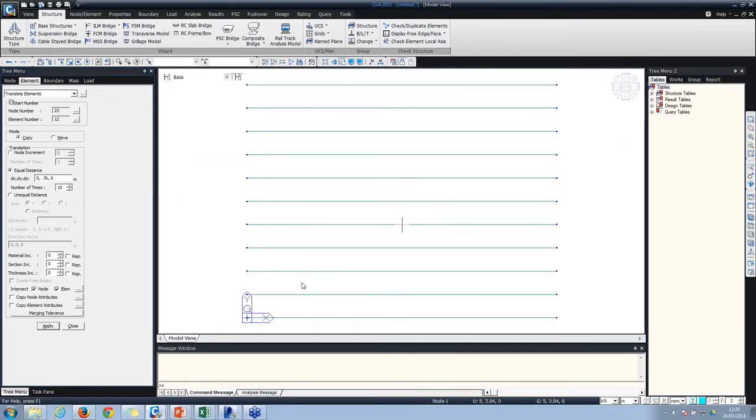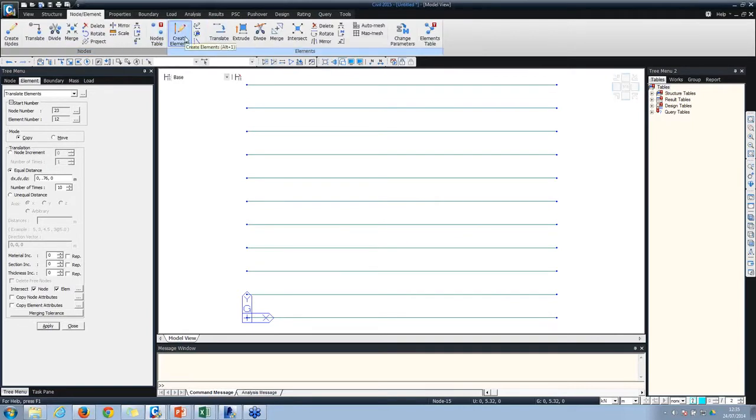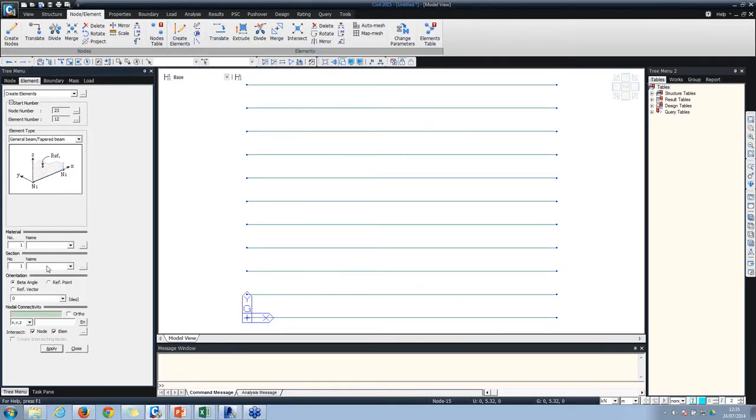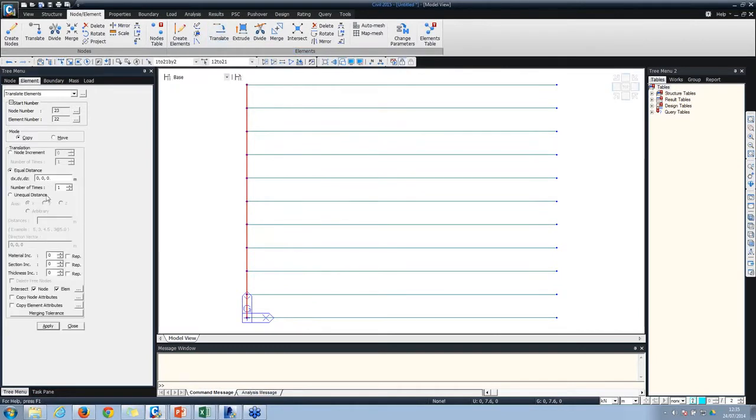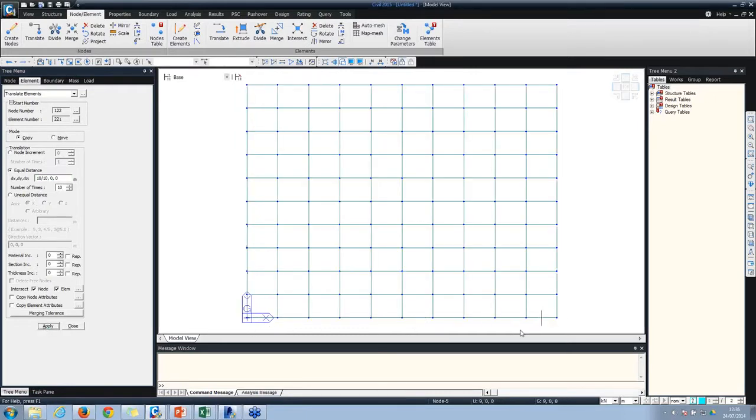Apply, and then draw the, so these are my main girders, main pre-stressed girders, and then draw the grillage, transverse grillage members, and then simply, let's say, copy them. Okay, so simple creating and then copying them. Okay, say 10 times. Okay, so it's a 10-meter span, and we have got 10 such pre-stressed beams.